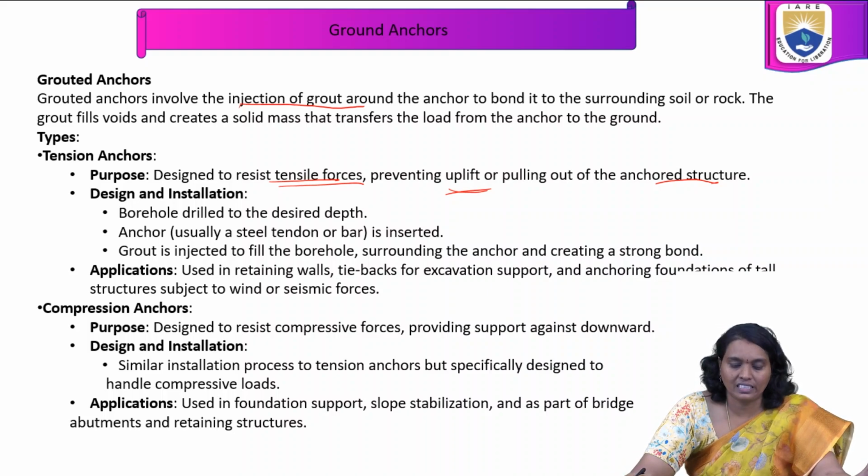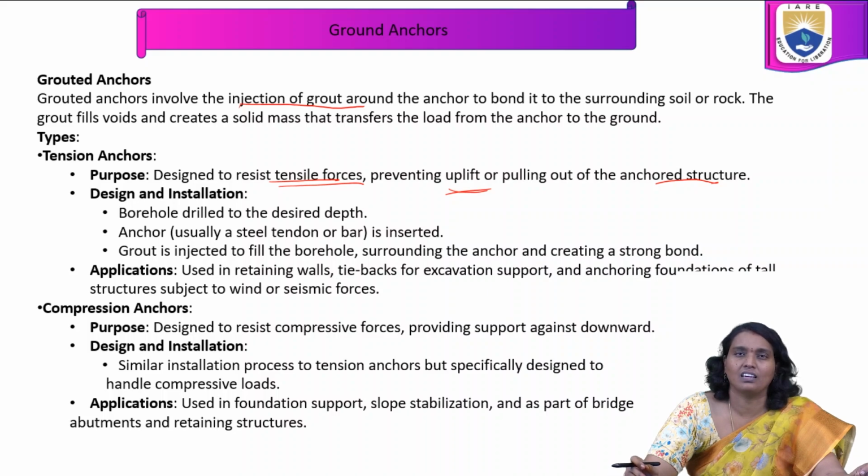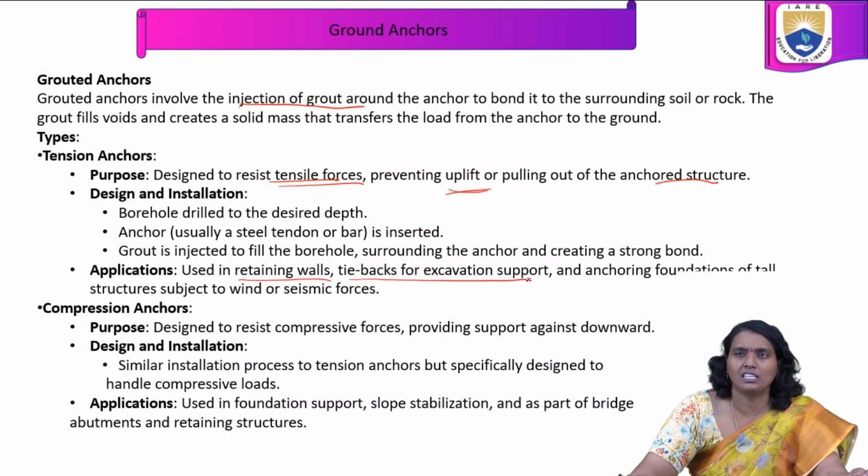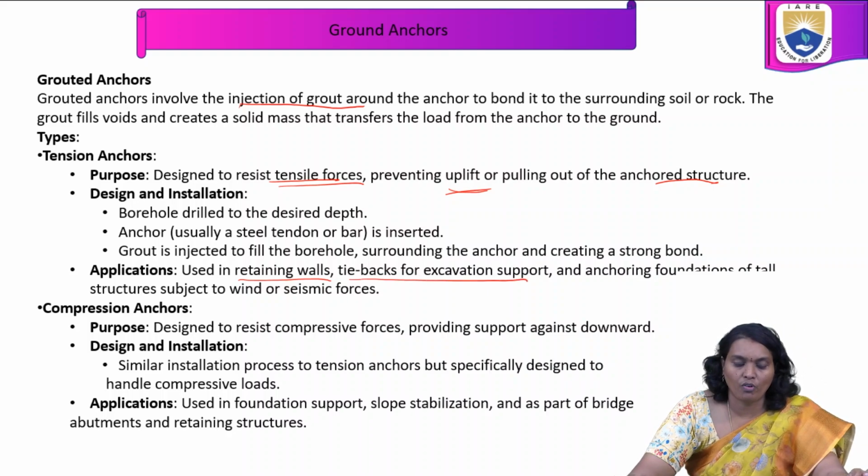Grout is injected to fill the borehole surrounding the anchor and create a strong bond. Tension anchors are used in retaining walls, tiebacks for excavation support, and anchoring foundations of tall structures subjected to wind or seismic forces.